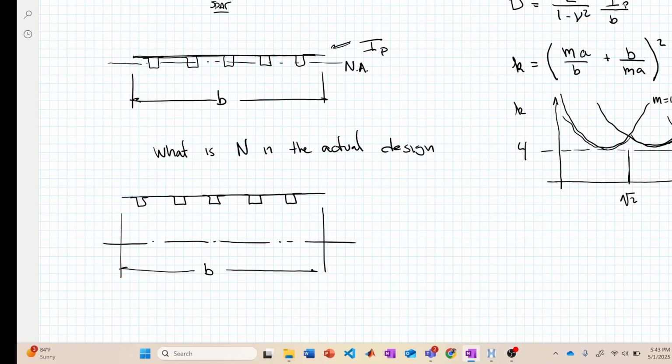So again, it's going to be the same thing. We are going to get that the force is equal to the change in the moment, just like we did for the stringer, over the rib span. Q, that's going to be Q of that whole top plate system, right? Over I, and this is I for the entire wing cross section, I should say.